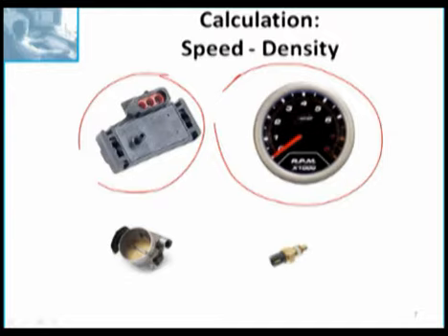If the MAP sensor is unresponsive, fuel trim could be lean off idle. So what I'm talking about is a MAP sensor that doesn't change when you open the throttle. That's fairly easy to check by looking at scan data. What's hard to check is to see if a MAP is out of calibration. If a MAP is out of calibration, fuel trim could be lean under all conditions. So really the best place to test a MAP sensor is key on, engine off.